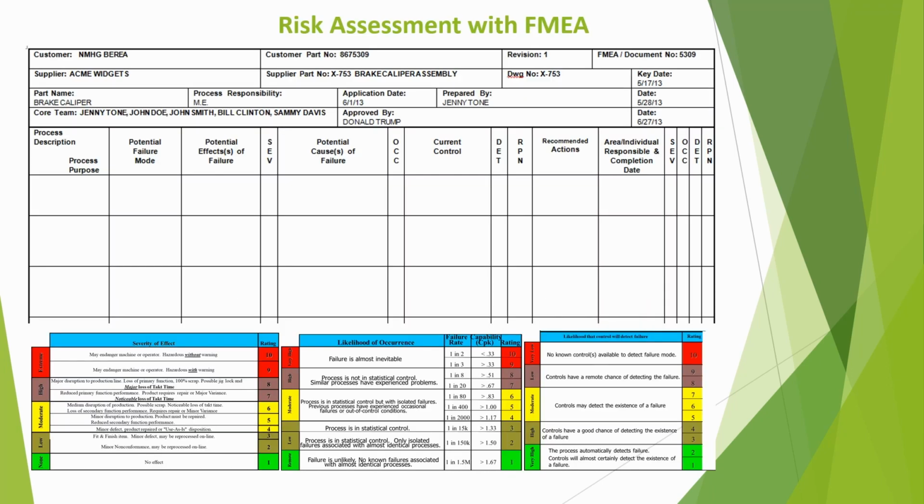Now let's understand with an example. In an FMEA risk assessment sheet, casting attach torque is the process being analyzed. The potential failure modes are over torque, under torque, and cross thread for this function. Potential effect of over torque is casting fracture, and potential effect of under torque and cross thread is casting separation. Severity ratings for each failure mode based on the severity rating criteria are 10, 9 and 9 respectively.